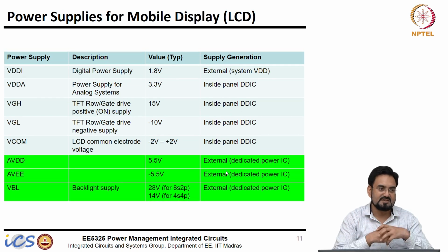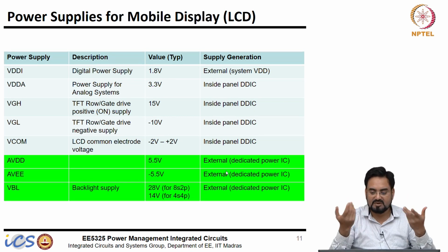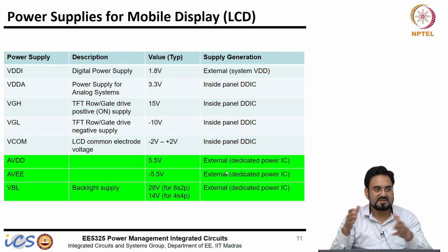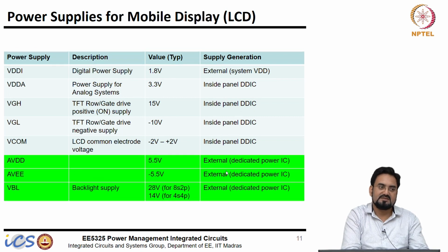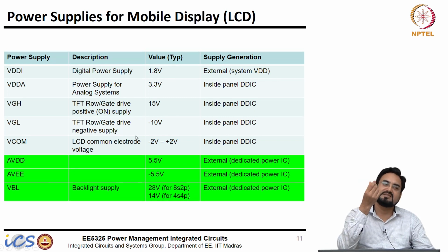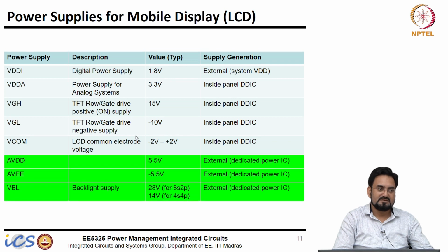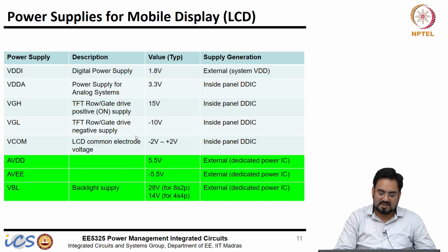The brightness is changing. So if brightness is changing at 50 hertz, then our eyes can see it, but as you keep on increasing the frequency, even if it's flickering, our eyes cannot see. Because our eye is more like a low pass filter, so beyond certain frequencies, if you go to the order of kilohertz, we can hardly see. If you closely look at your tube light, you can see a little flicker. But if you have an LED light and you turn it on and off at a very high rate, 1 kilohertz, then it will appear like a constant light.